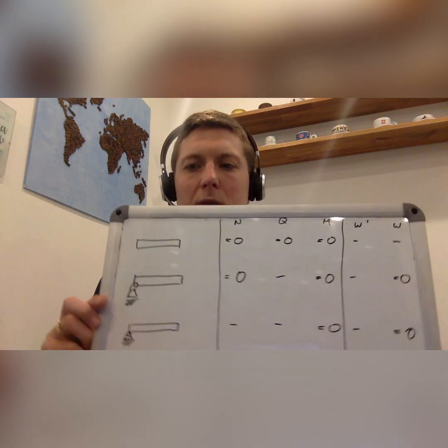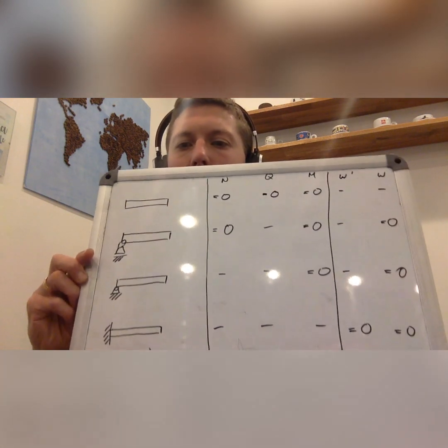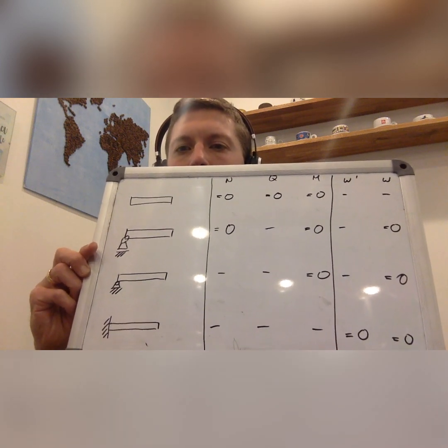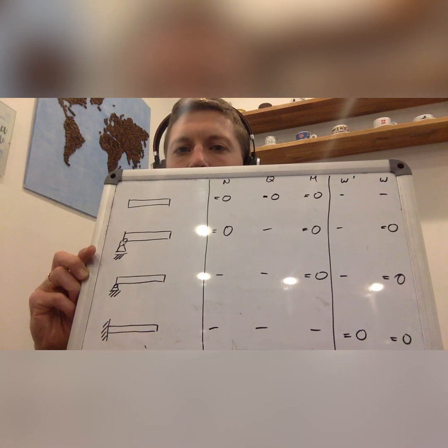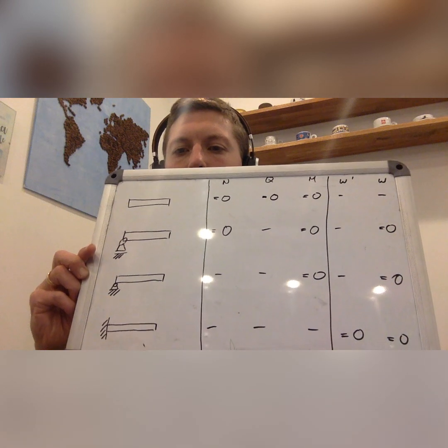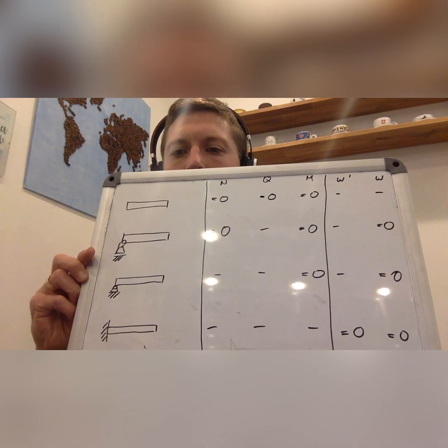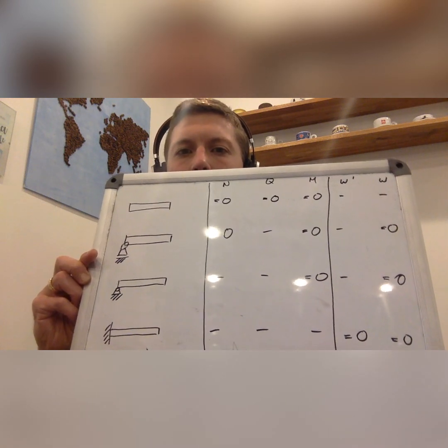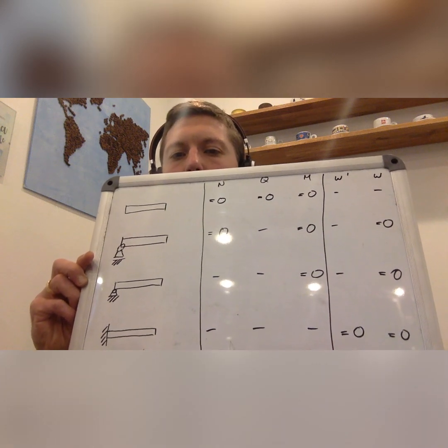So that means, to sum it up, for a fixed bearing, you could only state two boundary conditions, and in this case only kinematic, so geometric boundary conditions. And this will be helpful for solving our problems.